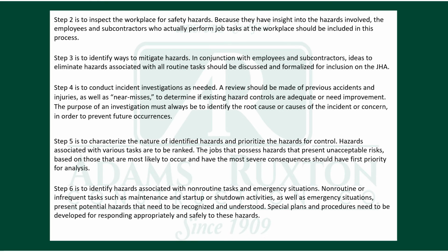Step 6 is to identify hazards associated with non-routine tasks and emergency situations. Non-routine or infrequent tasks such as maintenance and startup or shutdown activities, as well as emergency situations, present potential hazards that need to be recognized and understood. Special plans and procedures need to be developed for responding appropriately and safely to these hazards.